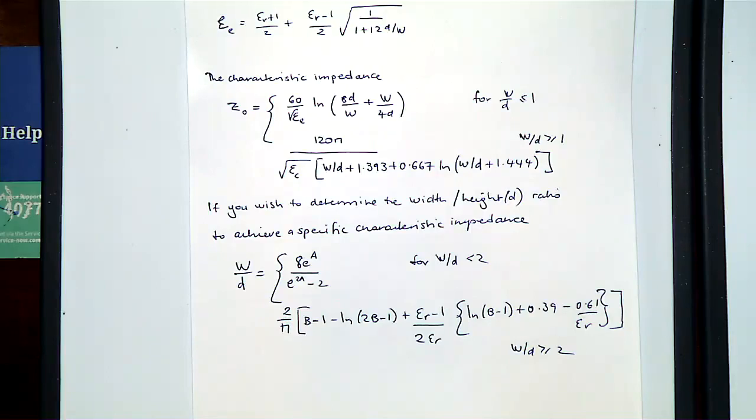The thicknesses are usually predefined, at least on a chip, but on a PCB board you can choose the thickness of copper to an extent. There are certain options at your disposal. But generally the width also depends on the resolution of that process. So you can't design arbitrary widths either, right?